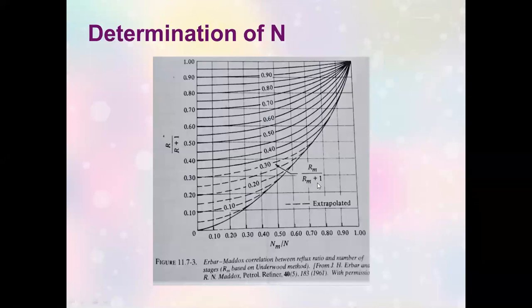So if I have the equation of my feed line or my Q line, which I gave you already, and the equation of my enriching section operating line, then in your algebra, you were taught that if you process two equations simultaneously, it's just like finding the intersection of two lines. The intersection of the feed line and the enriching section operating line would be your pinch point.